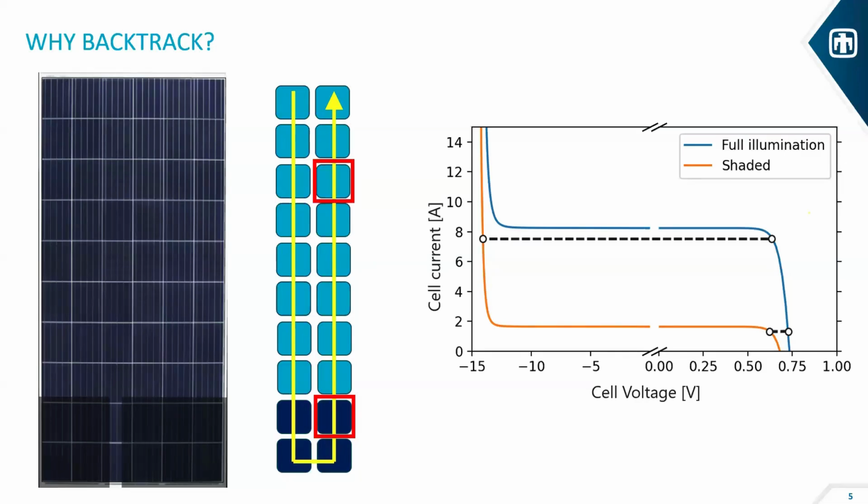So even though, of course, we have an irradiance reduction because of shading, the effect on power is much greater. It's like an order of magnitude, in some cases, larger. So by backtracking, maybe we get a percentage or 2 higher energy losses because of incidence angles, but we have that same irradiance distributed evenly. So all of our IV curves are going to be looking identical.